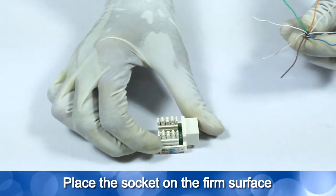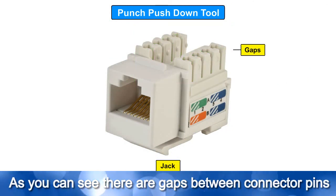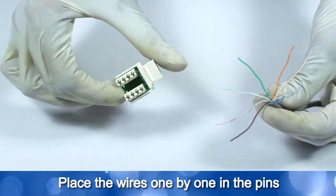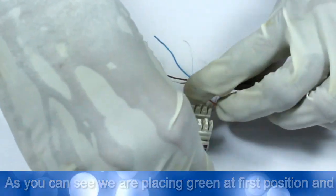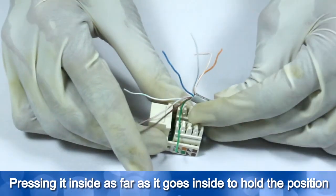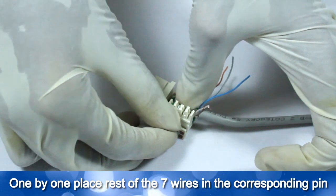Place the socket on a firm surface. As you can see, there are gaps between the connector pins. As per the color marking on the side line under type B, place the wires one by one in the pins. As you can see, we are placing green at the first position and pressing it inside as far as it goes to hold the position. One by one, place the rest of the 7 wires in the corresponding pins.